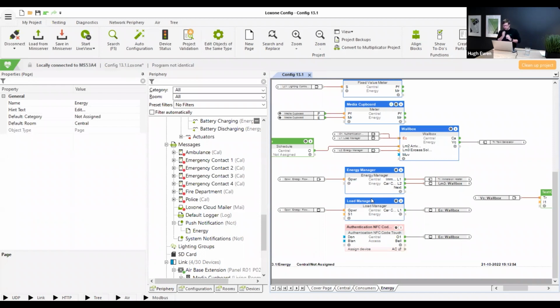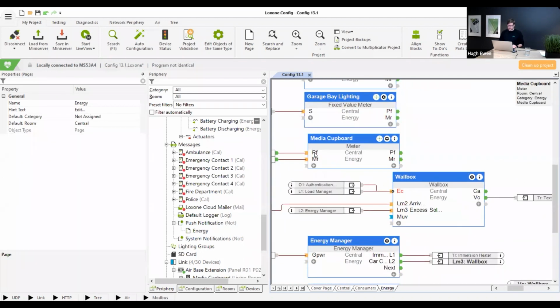Okay, Dave, on the meter block, you connected meter reading and power flow. Can you just use the power flow input on its own if you only have this data available? Yes, of course you can. You can just connect power flow and it can do the rest for you. You can see there in the description, if only this input is used, the meter reading is also calculated from it. So if you don't have the meter reading for whatever reason, you can just use power flow.